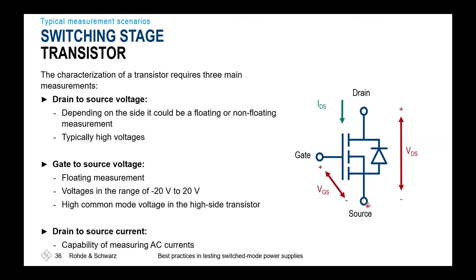So even if you're connecting the P and N port of your probe to the same testing point, which typically will be the floating potential at the source, you'll see some remaining voltage ripple coming up from the switching event from gate to source. And that's due to this limited common mode rejection ratio inside your system.